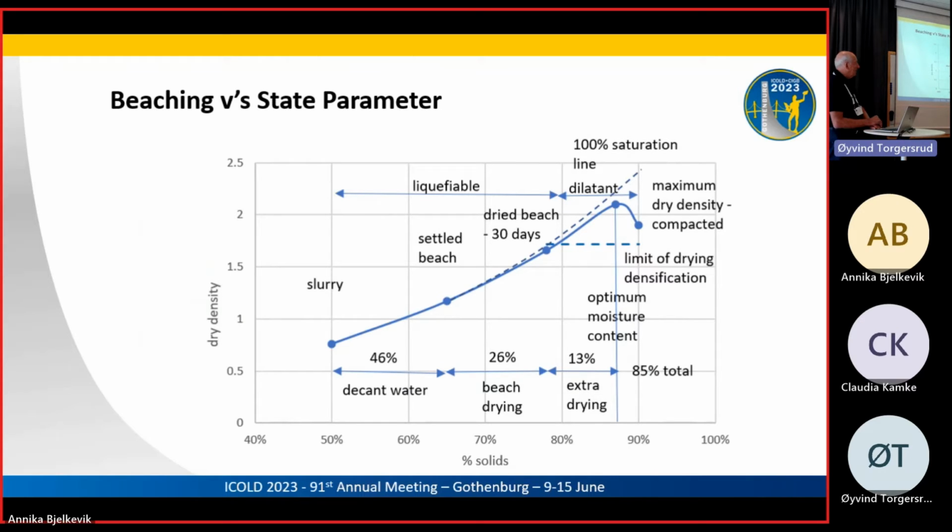And it is possible by mechanically working the tailings to actually get to that situation of removing more water and getting to a much higher density. In this case, you can see that the maximum dry density is over 2 tonnes per cubic metre, whereas most of our dams we're getting around about 1.5, maybe 1.6 for that particular density of material, or SG material.